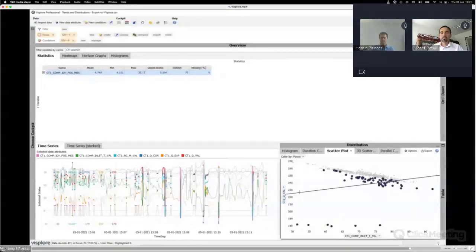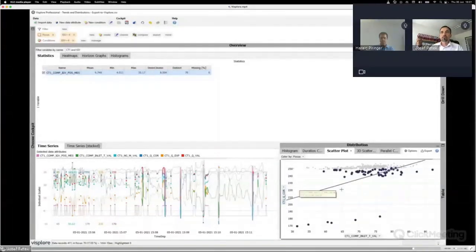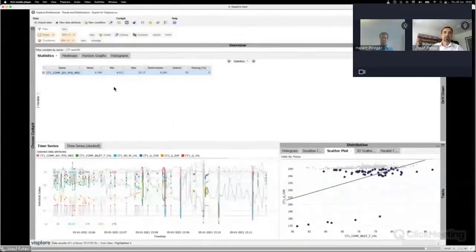It is also the case for the actual power output. And finally, it's also proven if we look at the corrected power output. So in this case, with the help of Visplore, we have been able to identify that this particular engine offers multiple baseload selection modes in its control system, each assigned with a different max position for this IGV angle.